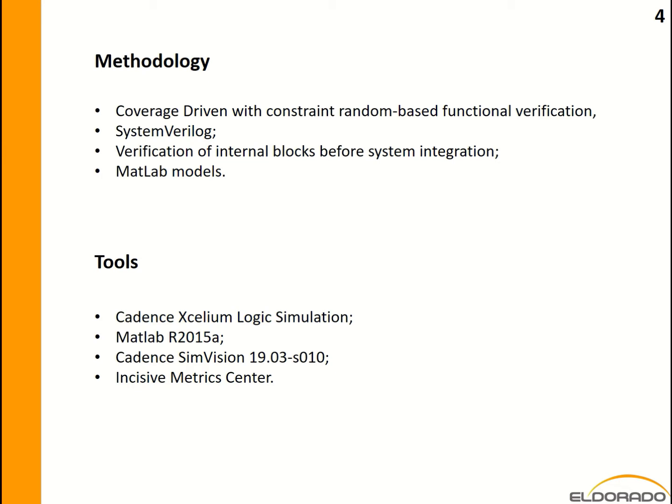Another methodology is formal verification using Cadence JasperGold. Although it's not being used in this project, the possibility of using it is considered. Some MR-FSK blocks of the modulator and demodulator were also tested in a separate testbench and performed sanity checks to avoid bugs after the integration. Also, some MATLAB models were developed to test some functionalities.